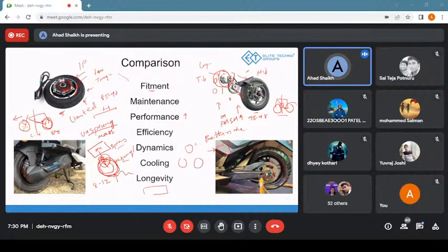So basically, the climatic conditions, like the high temperatures nowadays. It's summertime, so the battery couldn't sustain that. That could be one reason. And the BMS, it couldn't balance the cells, or the battery thermal management which was used, and the bus bars which were connected, I suppose were not capable of handling that much temperature. That sort of thing might have affected it, but I am surely going to research that, and wherever I get to know about it, we can discuss it in upcoming sessions when we talk about relevant things.